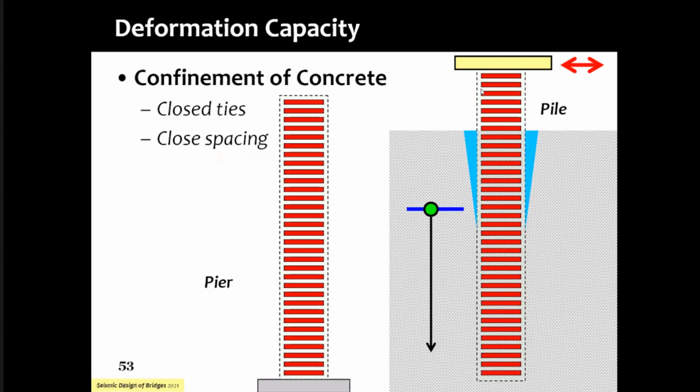The answer is, at the beginning of shaking, you will see that the shear force is like a cantilever. The shear force is constant all through, right? At the beginning of shaking, the hinge can get formed at the support here, and as the shaking becomes stronger, the soil can get separated. But if the soil is caving in, you're in trouble again.